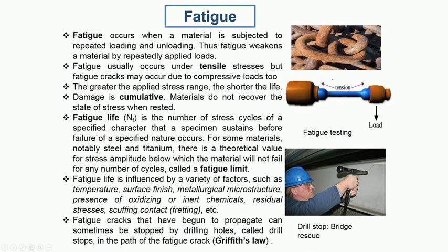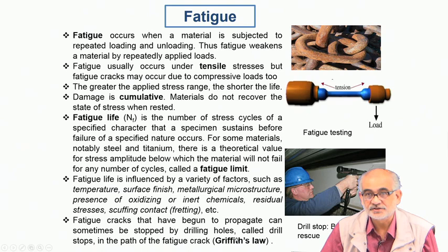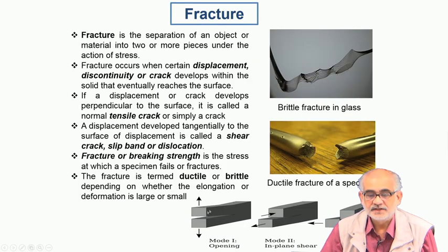So if you make a circular hole, since the radius is extremely large compared to the radius of a sharp crack tip, in such a situation you would definitely expect the crack to get arrested because of the intervention of the circular hole ahead of such a crack tip.